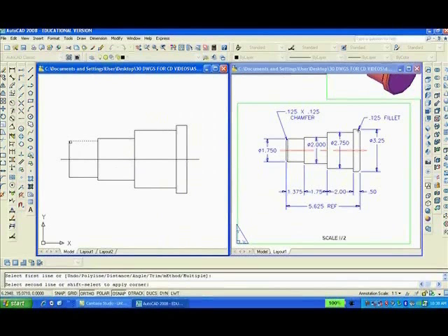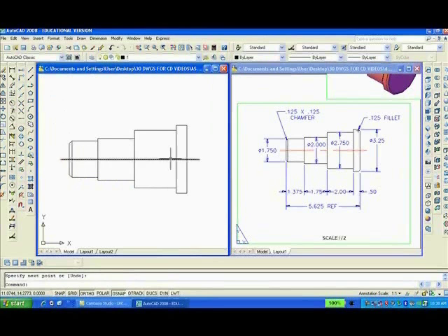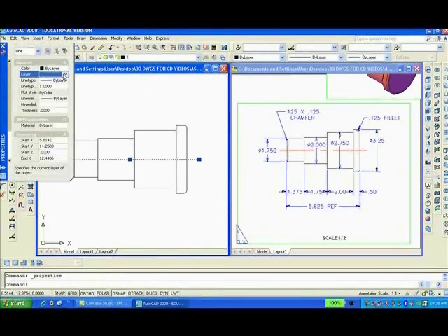Now all I got to do is pick the 2 lines in the intersection like that and that. Then draw a line connecting both points. So the chamfer is done. The other end asks for a fillet, so I'll type F, enter, R, enter. Instead of 0, I'm going to type 0.125. So we're going to have a radius on this corner, like so, and so. And I'll select the center line, go to Property, change the layer from 1 to center.